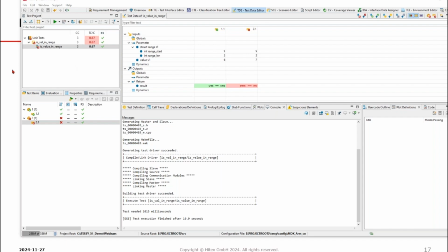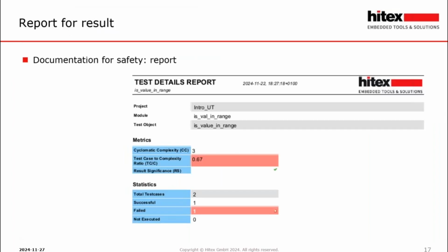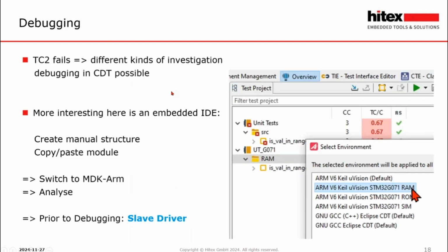Let's think about where the test has been executed. Here it was running on the PC, on the CDT, but in general, you might run the test on your hardware or on your simulator, depending on your environment. So here I will introduce a microvision. It's a Cortex M0 Plus. And I do not like to always destroy the flash by flashing. So I will execute the test from the RAM. Very simple. So let's do a new test.